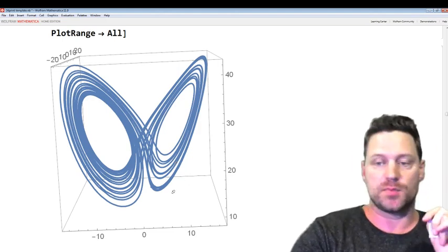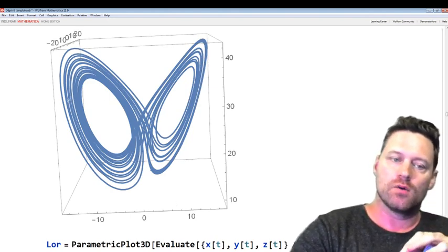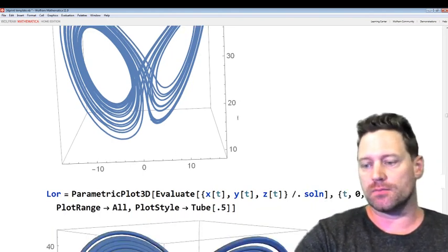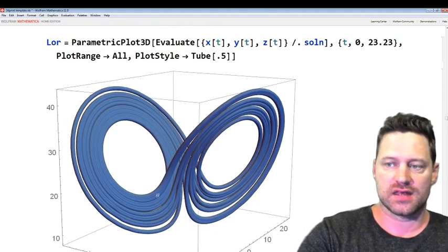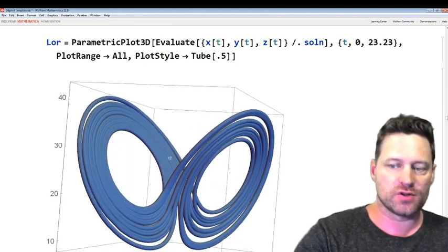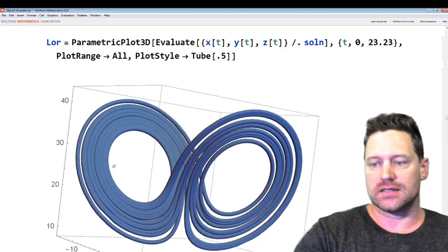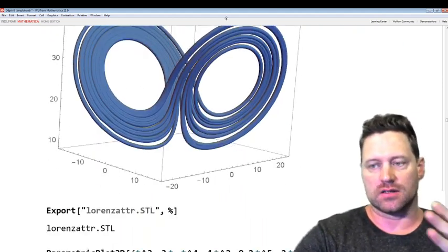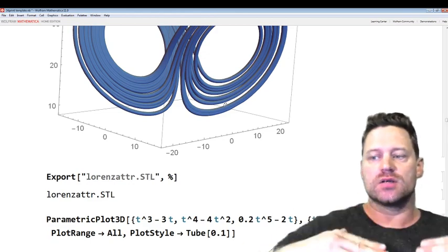I've also 3D printed that. The results were a bit mixed because, well, you see it's quite stringy. And here we see that the thickness has been given. All right, so now it's suitable for 3D printing, but again, as I said before, it's a little problematic to do so because when you 3D print, you've got to build supports, right?